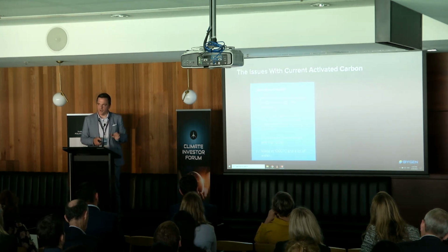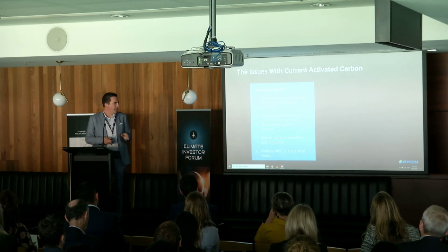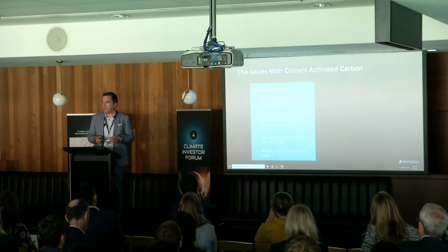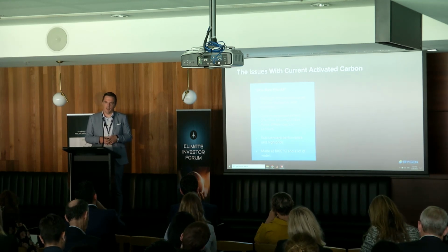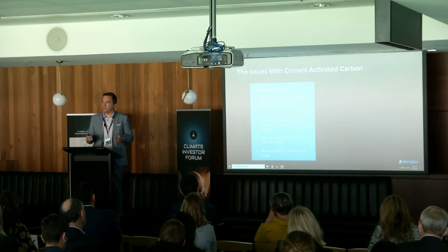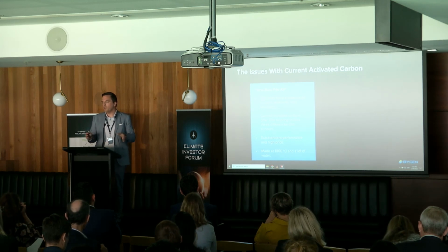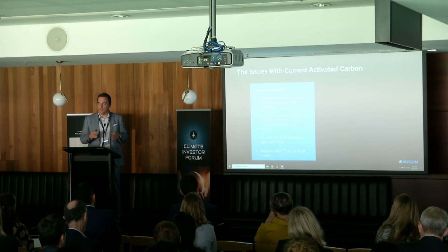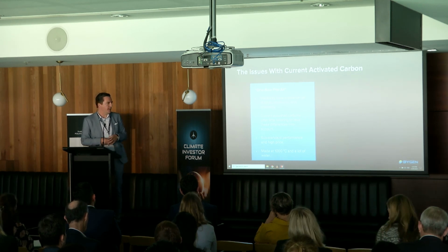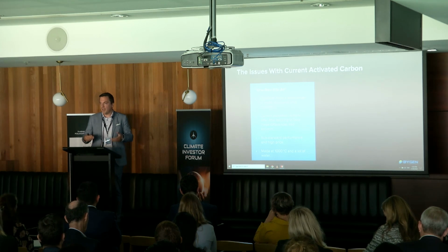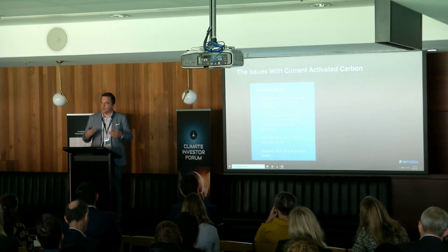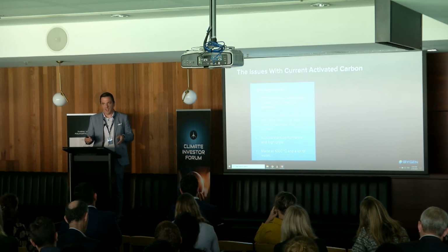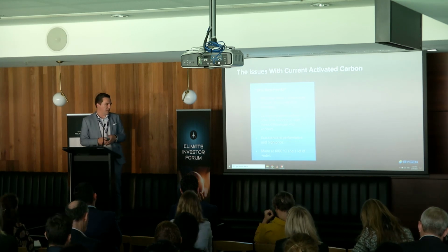There are issues, though, with the current activated carbon in the market. The first of these is what we call the one-size-fits-all approach. All those diverse applications I showed you earlier, you're basically trying to bind chemicals that have hugely different sizes, structures, and chemistries. And the current activated carbons offer little to no tailoring to take those differences into account. So customers end up paying very high prices and get relatively poor performance. The reason they have to pay so much for it is that the way it's made is extremely energy intensive, needing 1,000 degrees and lots of water.